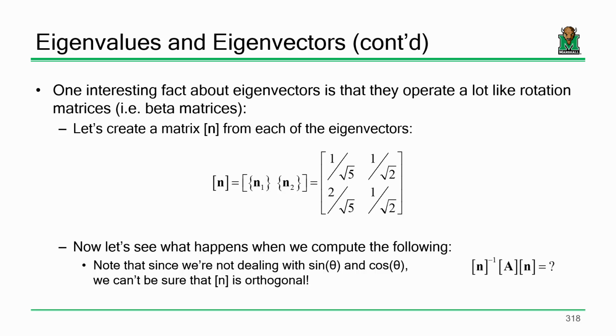How many of you remember that whole thing called Mohr's circle? Remember, you're given a stress state, and you are trying to determine principal stresses. In other words, I'm given a stress state, but that stress state is based on a coordinate system that I just made up. I just said, okay, this is my y-axis and this is my x-axis. But really, instead of this being the coordinate system, maybe this one is the coordinate system. Maybe that's what I need to look at. So what's the difference? It's all about your angle of rotation.